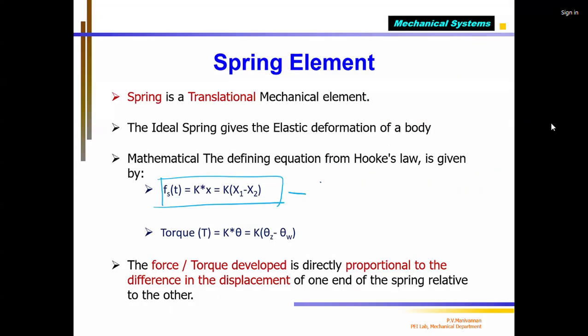So now this is called the mathematical equivalence of a spring, the mathematical model. Once you have this mathematical model, without making the spring, I can find out what will happen. In this equation, F s of t is nothing but Ks multiplied by delta x. Delta x is the output, F of s is the input, and Ks is called the system parameter.